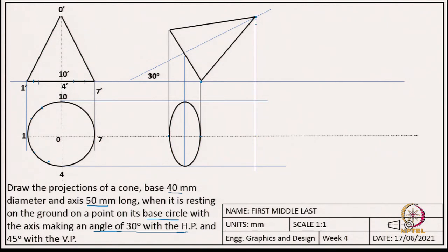For the apex, you follow this vertical line, and similarly this horizontal line starting from O, and you identify the apex. Once we know the apex, we just need to join it with two lines such that it gives the appearance of a solid. Okay. First the ellipse, then the apex. Once you get the ellipse and the apex, then you need these two inclined lines to capture the complete cone. Okay. So, now we are done with step 2 with both the front and top views.